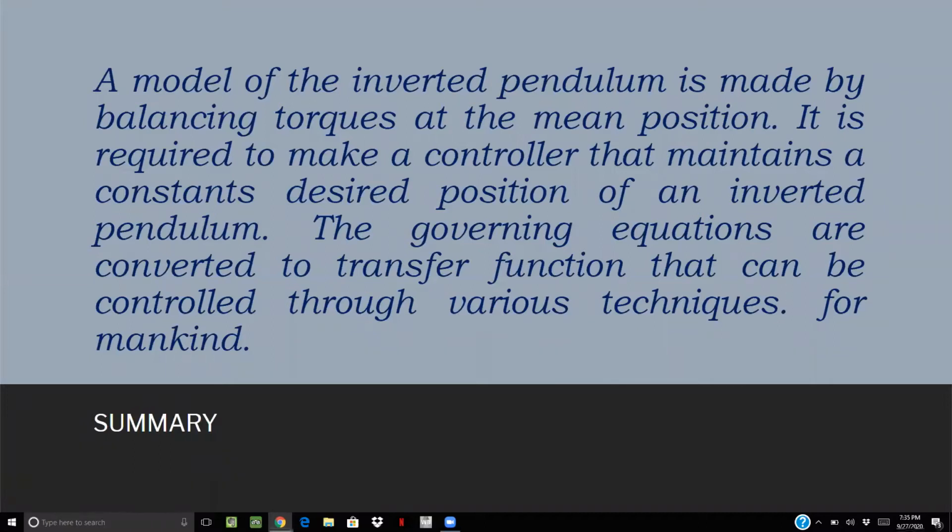A larger mass makes the pendulum fall, but the spring can prevent that. However, the spring will oscillate. So to help, a damper is used to minimize the oscillation, but the damper can create steady state error. To account for this, an input motor is attached and converts current to torque to help the system achieve the goal in the desired time and specifications.